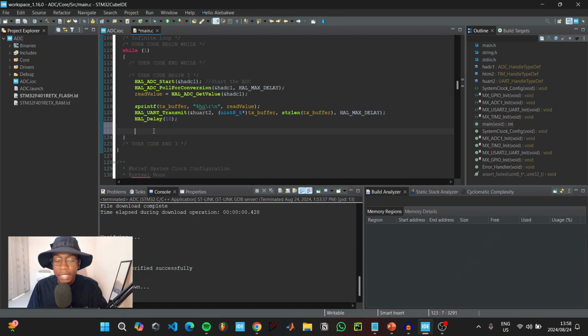1. When this is done, we need to map the ADC value to a variable that will control the duty cycle of our PWM signal. So the idea is that when we turn the knob on our potentiometer going from left to right, from the low value to the maximum value, we should see the brightness of the LED increasing and decreasing as well.